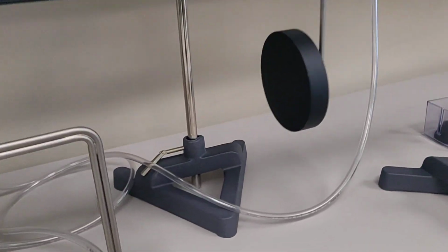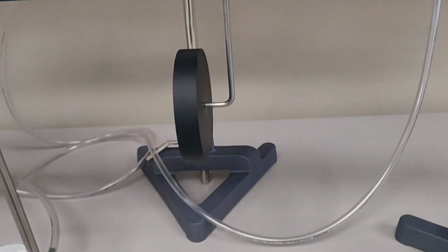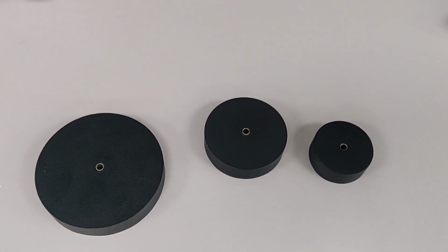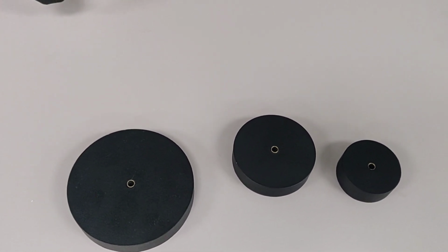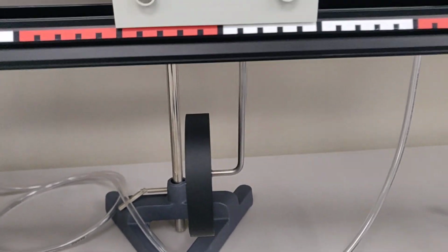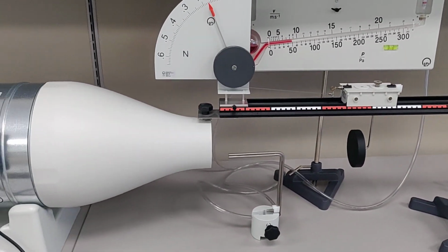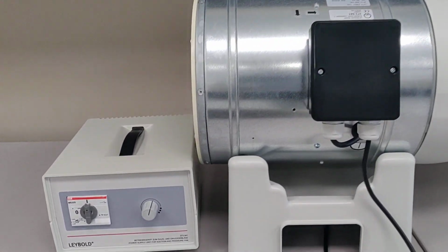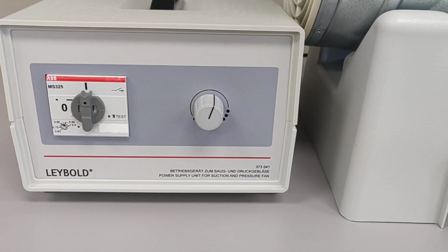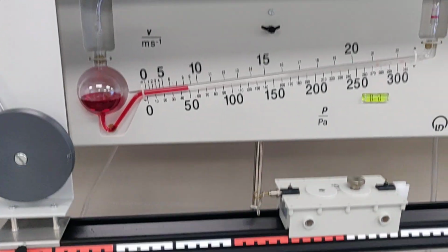And the disc that we have here is the biggest diameter disc, which is fixed on that hinge. Here we can see the other two discs, medium diameter and the smallest diameter, and the circular slot available at the center of the disc, which will help us to fix it on that hinge. So that will be your test 1 at one specific setting of this fan speed. That is one particular setting where you have the knob with the black marker. One setting of the fan speed. You have the drag force, the pressure, and the velocity for that disc.